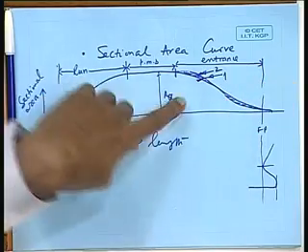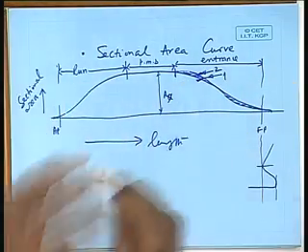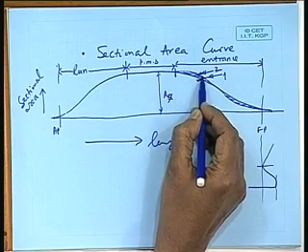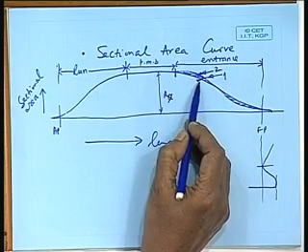Shoulder. In the case of curve 2, the shoulder is more prominent, and in the case of curve 1, the shoulder is less prominent. Now, we have seen about wave resistance, wave making resistance. Curve 2 will give me a more prominent shoulder wave. So, looking at it from this point alone, I would prefer curve 2 to be worse than curve 1. That is, I will prefer curve 1, where I have a smoother shoulder.